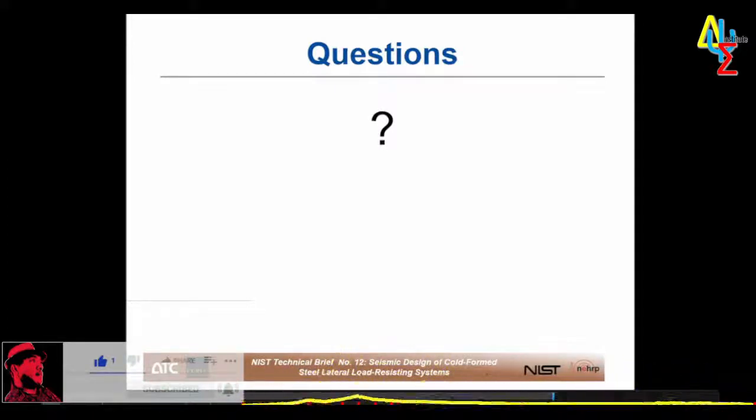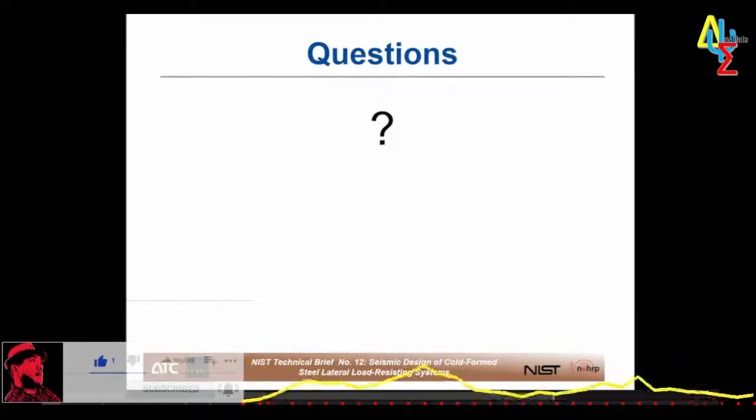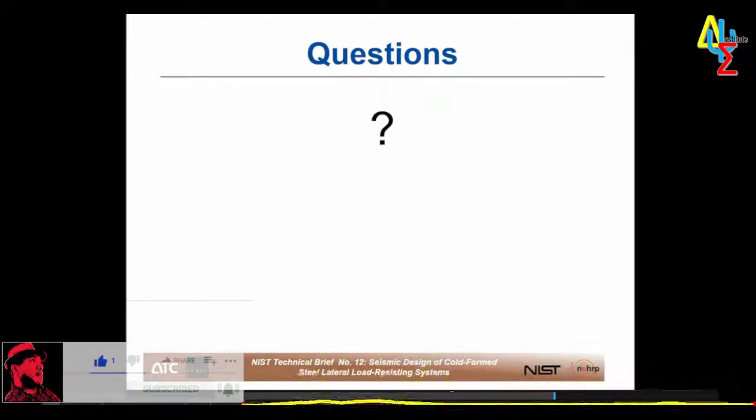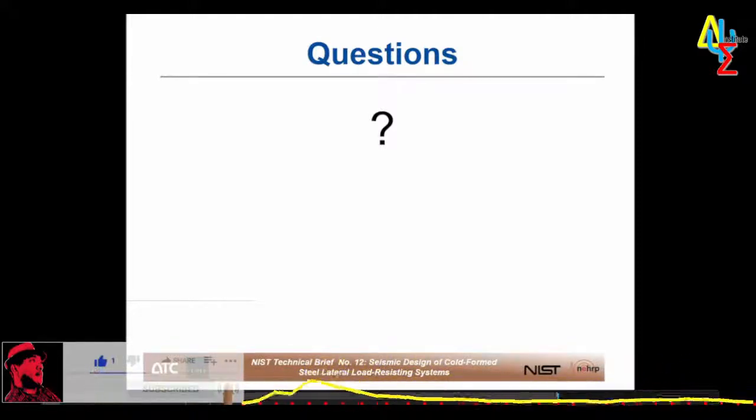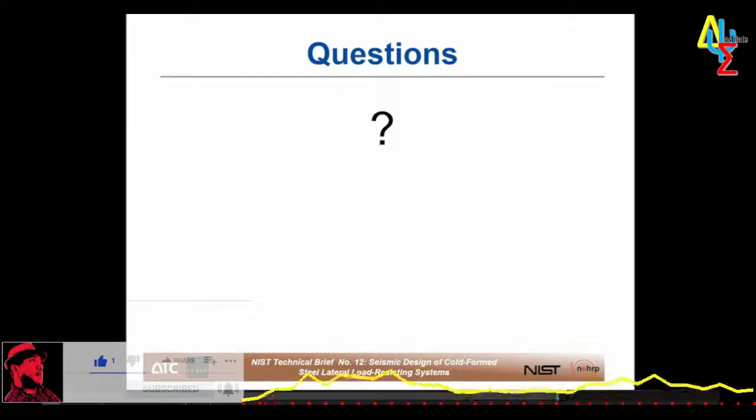I would say that any type of plank system, if properly designed for the right strength and all the connection systems, I'm sure can work just fine. There are considerations that would have to be made with regard to how the planks interconnect for continuity. I've talked a lot today about, for example, collectors and elements in the seismic load path. So concrete planks, of course, are heavy, so they're generating a lot of seismic force, but also, the interconnection between those and whatever collector type system you're using is going to be super critical.